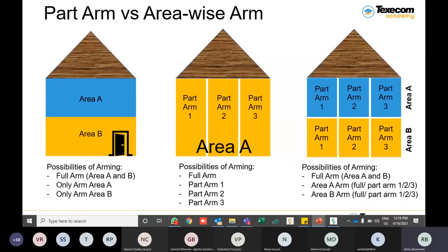Are you understanding the requirement? The customer wants that the PIR motion on the ground floor area is not armed, that the PIR remains deactivated, and all the other sensors in the ground floor remain active.